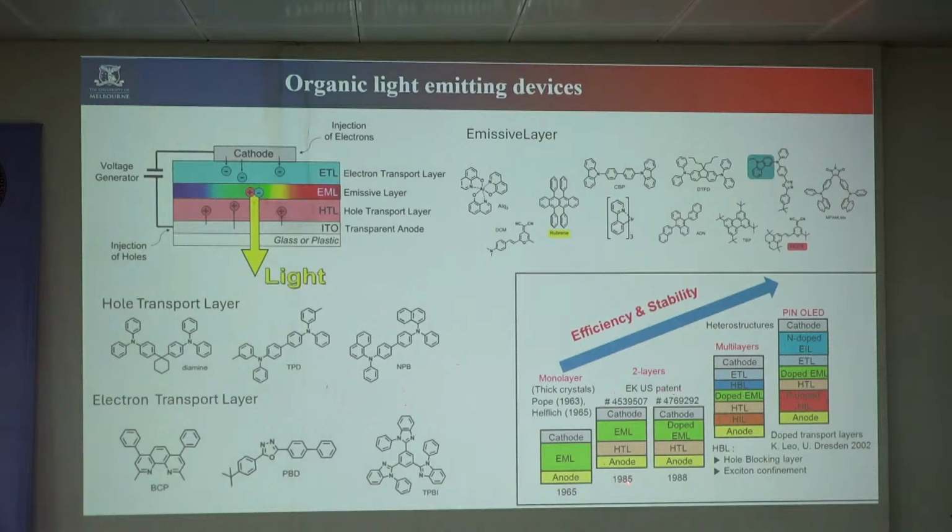That is in 1985. After that, they used the hole transport layer, emissive layer, then a doped emissive layer. Doping will improve the mobility or conductivity of the emissive layer. That's why people are doping. Then here is a somewhat sophisticated multilayer device. Here the anode and cathode are standard for injecting charge carriers, with the middle layer doped.